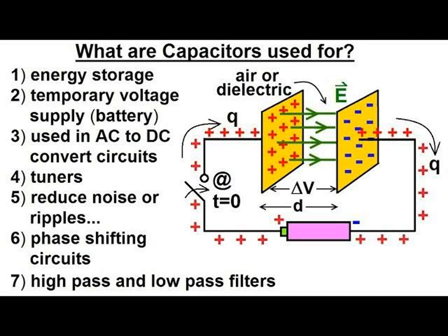Good. Now, if you want to charge this particular Leyden jar capacitor, all you need to do is connect the knob and the body of the Leyden jar capacitor to a source of power. It will charge it. To discharge it, you connect the knob, which is negatively charged, and the body, which is positively charged, to a bulb or a DC device, and it will power it and discharge. Once it gets discharged, you can charge it again. So that is a Leyden jar capacitor.